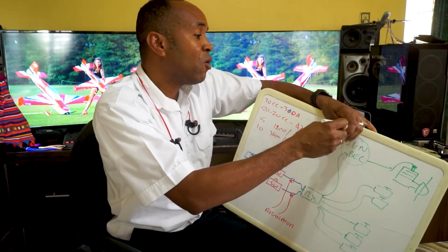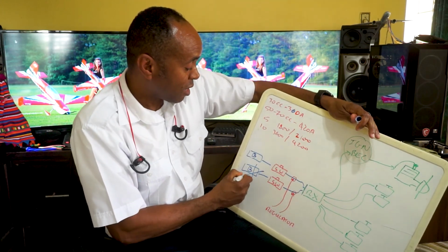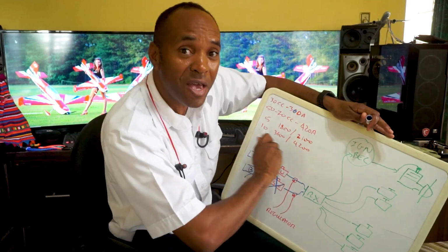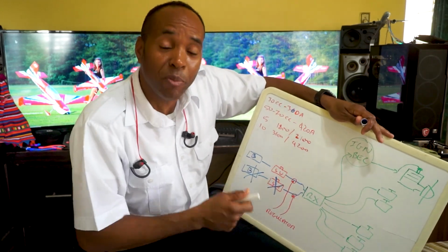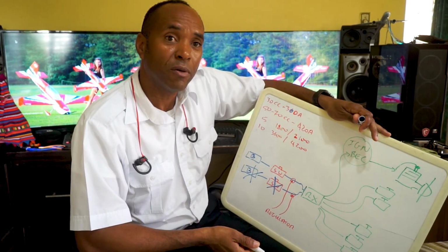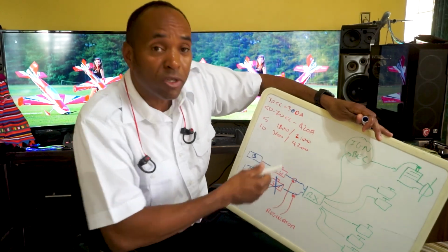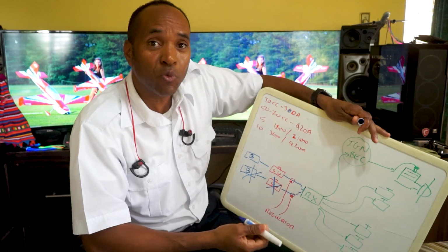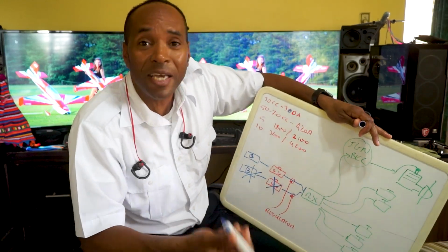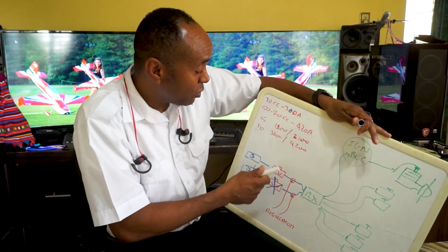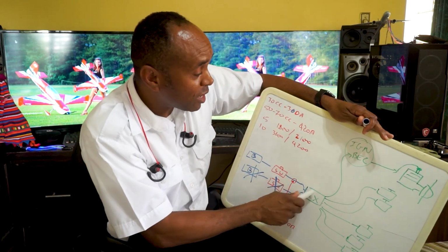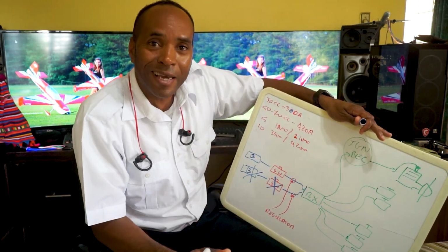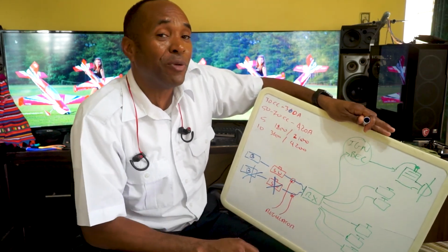Let us say one battery decides to fail, or one switch decides to fail. The remaining switch is going to have to be able to cover everything, or else you're going to lose your plane, right? In a 30cc airplane, mid-maneuver, the peak amps will be like 5, 6, 7, 8 amps. So therefore your battery, your switch, your receiver has to be able to tolerate up to at least 8 amps for a 30cc airplane.